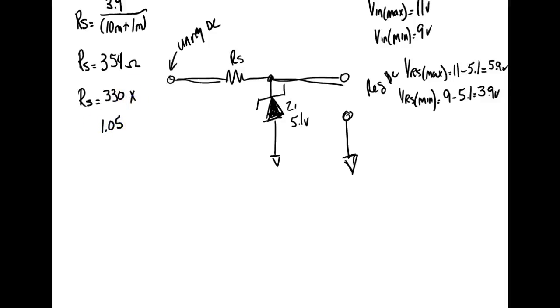And why is that? Yeah, so what we're doing is we're checking to make sure we cannot use a resistor bigger than that. That's the absolute maximum that would put it at IZK. So this guy here is obvious, it's going to be okay. And what do you come up with when you multiply it by 1.05? Anybody got it? 346.5. This guy right here is fine, as long as it's less than that. If it came up equal to that, then you'd probably go down one more, right? So RS is going to be equal to 330.